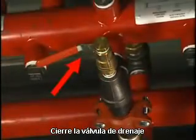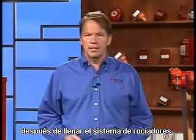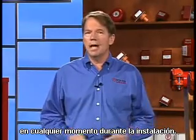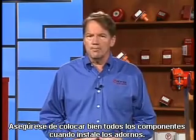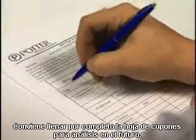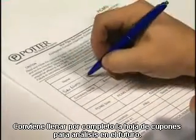Close the drain valve and open the coupon rack isolation valves after filling the sprinkler system. The trim can be assembled on the PCMS components at any time during the installation process. Just be sure to properly position all of the components when installing the trim. You will want to fill out the coupon card completely for future analysis.